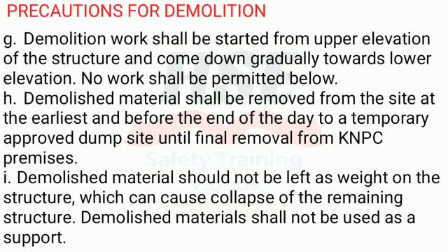H. Demolished material shall be removed from the site at the earliest and before the end of the day to a temporary approved dump site until final removal from KNPC premises. I. Demolished material should not be left as weight on the structure, which can cause collapse of the remaining structure. Demolished materials shall not be used as a support.